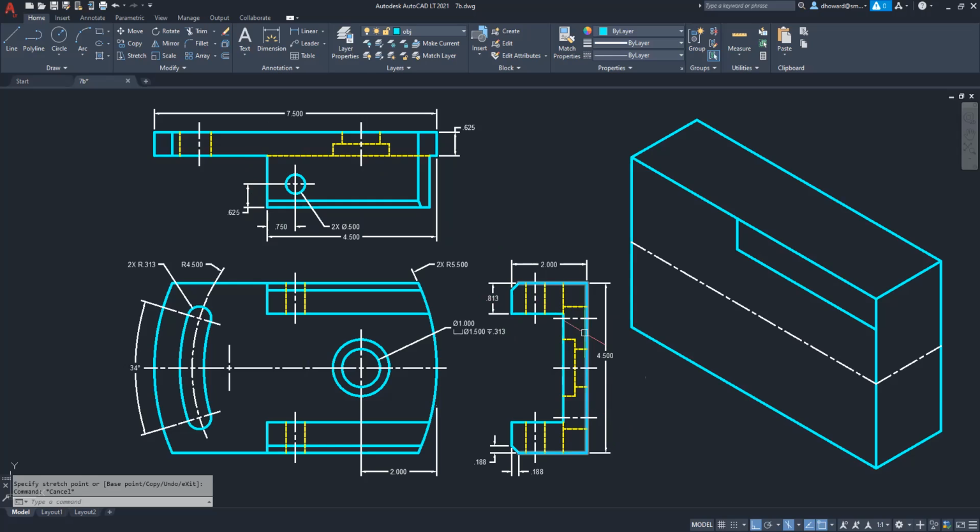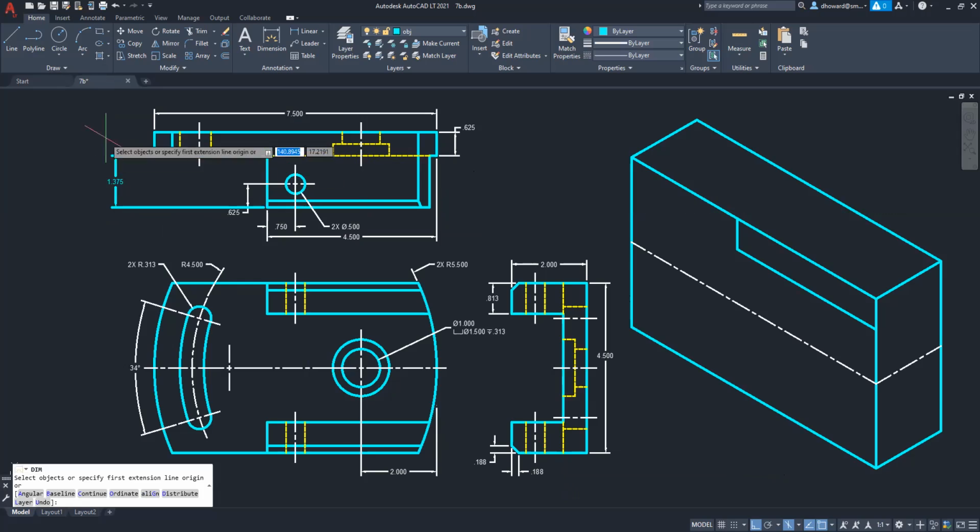That distance is not given directly. The whole object is 2 inches and the bottom is 5/8. So that would make this piece right here, its overall height, 1 3/8 of an inch, 1.375. So you could do that subtraction, or you could just come over here and dimension it directly if you wanted to temporarily. Just click those corners and there it is, 1.375.